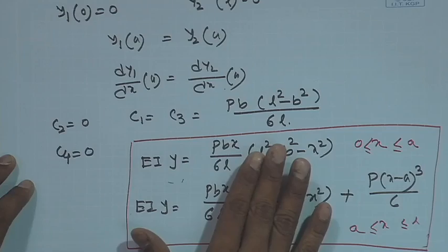So, this equation, the equation of elastic curve, is very important, not only for this course. You will see in future there are many occasions where you will come across this equation, and in many practical problems these equations are used. So, what we do next is we study two other methods: the moment area method and the conjugate beam method for determining deflection of statically determinate beams. But we will see that the premise of these methods are these equations. So, there should not be any confusion as far as the derivation and application of these equations are concerned.